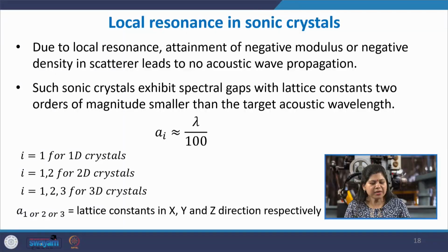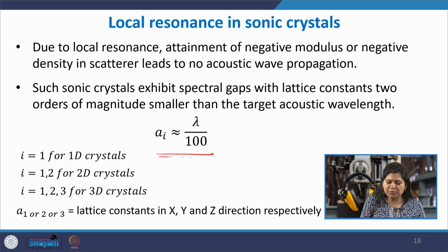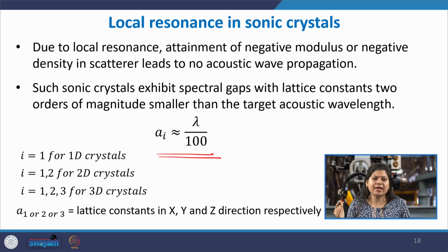Okay. So, typically these sonic crystals which are based on local resonance are designed these days such that, according to Bragg's law or Bloch's theorem, the spacing has to be of the same order as lambda. But now with the principle of local resonance, we can attain a spacing which is approximately lambda by 100, that is what is attained. So, we can bring down the overall size by 100 times using the concept of local resonance.